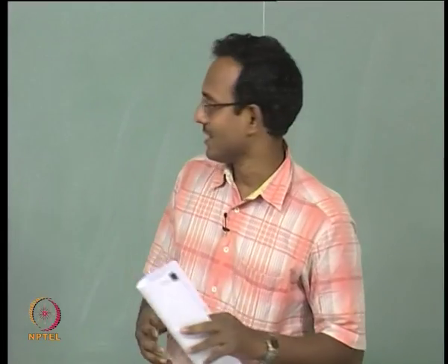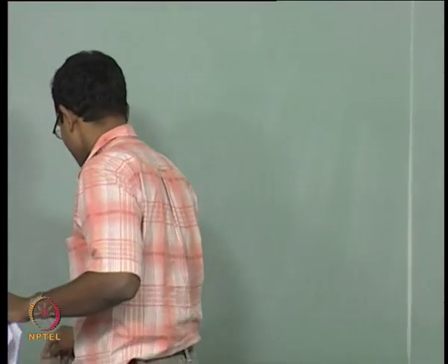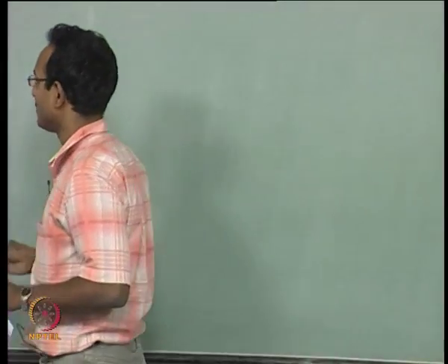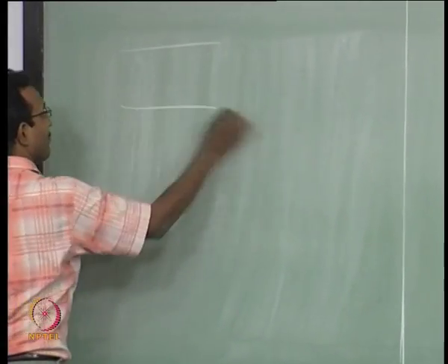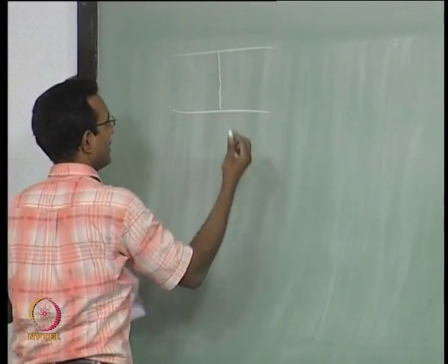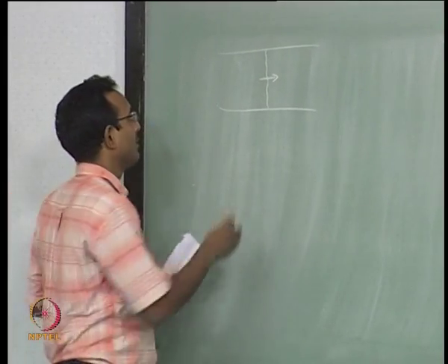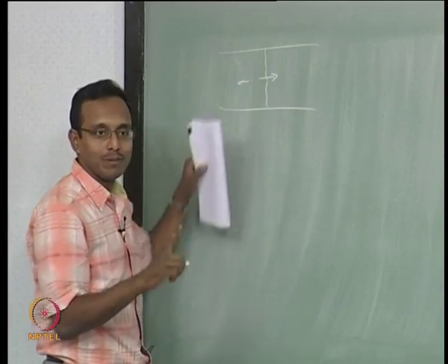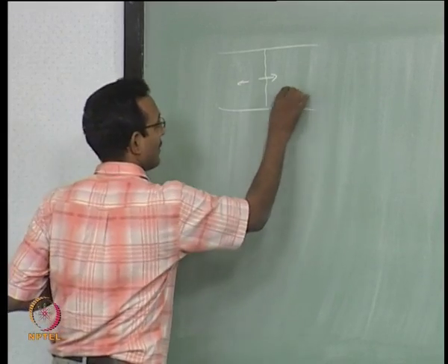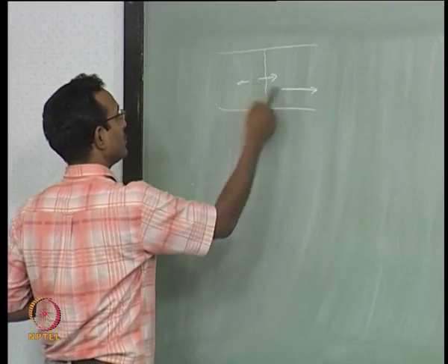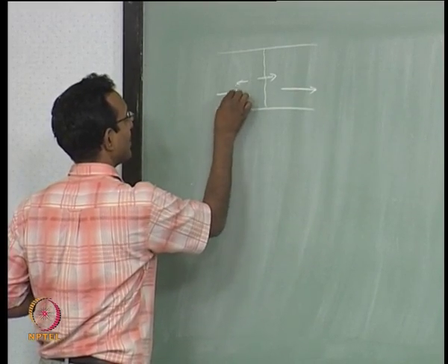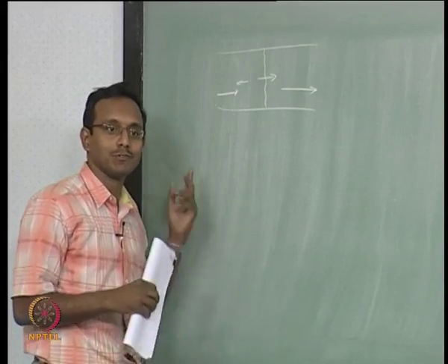Hello everyone, welcome back. We looked at simple one dimensional waves last class for expansion process, and we said that we have to look at it as if I have a flow, and if there is a wave and the wave is going like this, the induced flow part alone will be like this. If the flow is already having this big velocity, the induced flow should be added to it and it will be slightly lesser, only this much will be the final velocity. This is what we saw last time.